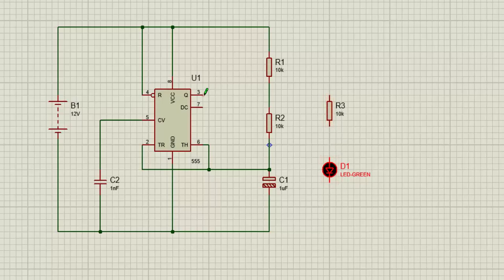Here I'm going to click on pin 3 over to the terminal of the resistor and drop it there, which creates a connection point between the two components. Do the same thing here, click and hold on this point, connect to the other point. Lastly, I'm going to connect the other point of the LED to ground.